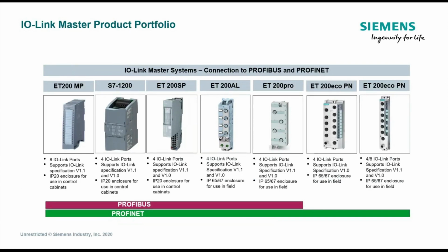One of the latest developments in our portfolio is this SP IO-Link Master. We came out with a multi-function interface that now supports both Ethernet IP and Modbus TCP. And with that new interface module, which I'm showing here with my demo, I have now opened up the world from Ethernet IP and Modbus TCP into the IO-Link world as well.